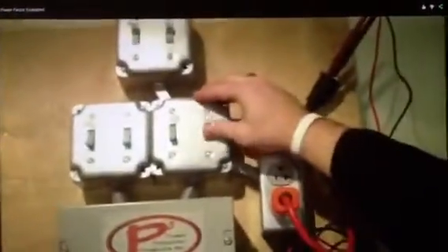So as we bring on the first motor load, you can see as we zoom in, the total power factor is 0.225. And now, as I would like to correct this power factor, I will start to begin bringing on some capacitors, flipping on the first stage.